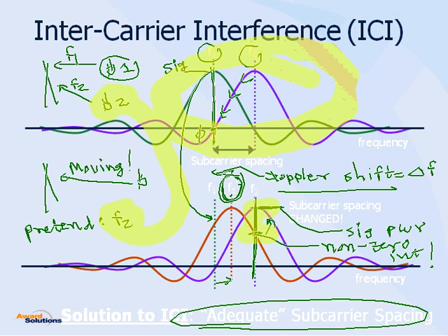Okay, but of course the pilot is a reference signal, and we will use pilot to do coherent demodulation. So that aspect will be working, but in terms of being able to compensate directly using the Doppler shift of pilot, it may be a little bit difficult because you have already taken the samples, and when you have taken the samples, then you have equally spaced subcarriers. So you have already picked the sample points in the frequency domain.